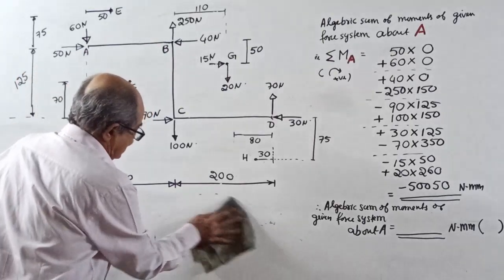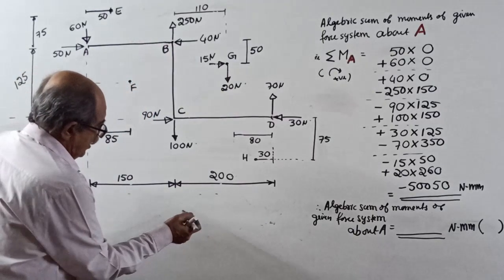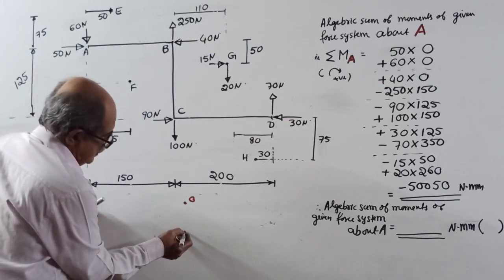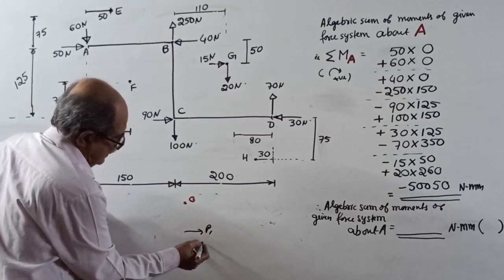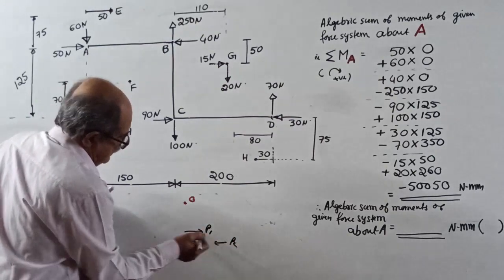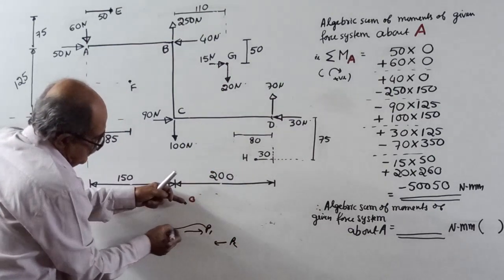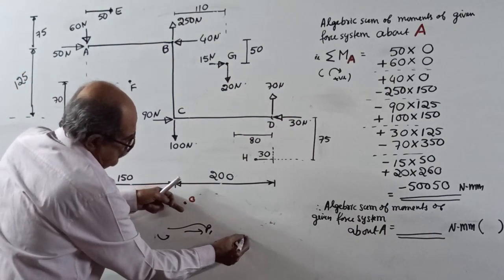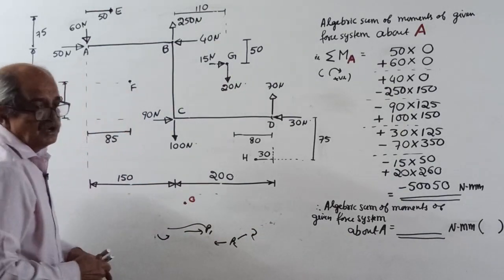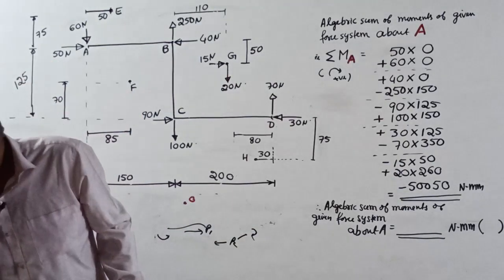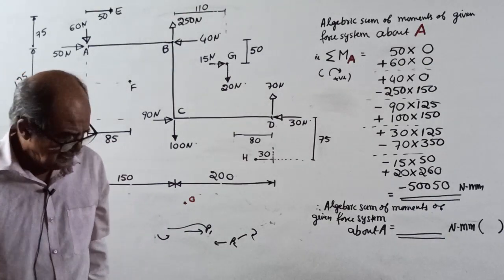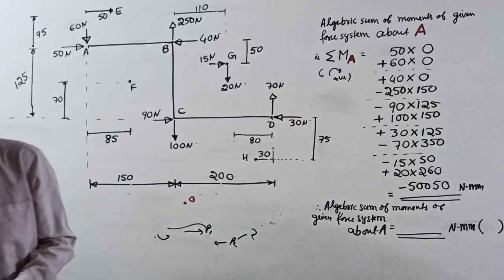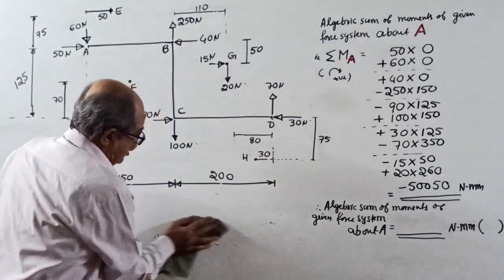Lastly, in case the point O is here, one force P1 here this way and P2 here this way. Now P1 will produce anti-clockwise, P2 will produce clockwise about this point. So never memorize that left will produce clockwise, right will produce anti-clockwise. Nothing like that. You hold at the point where you want moment, apply the force freely and decide clockwise or anti-clockwise.